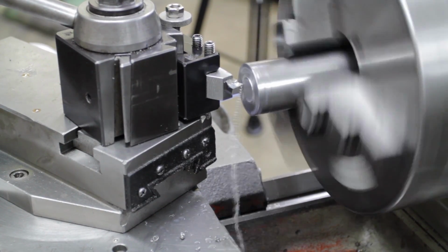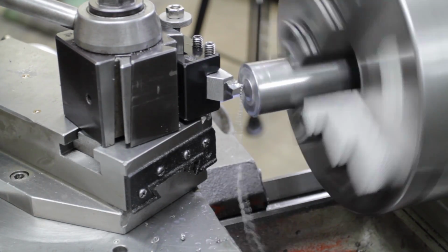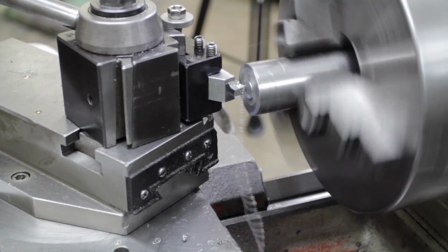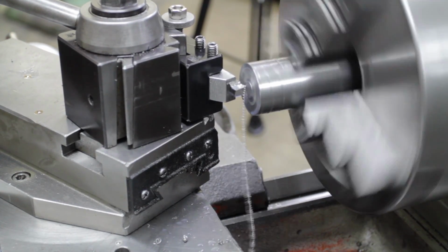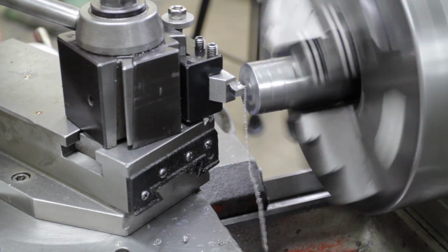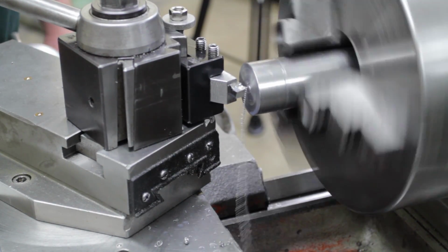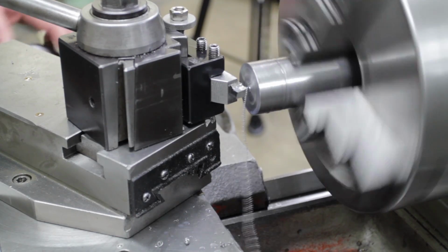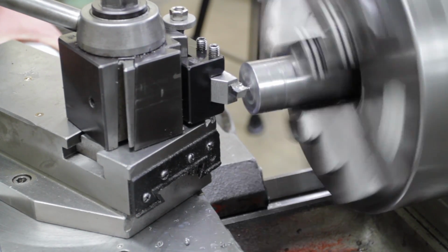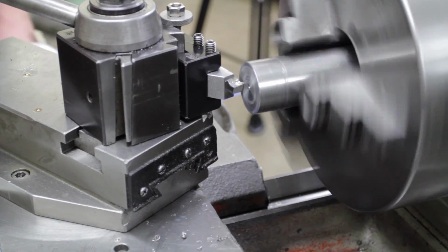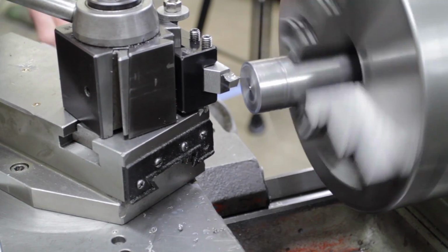So 20 thousandths is a pretty good depth of cut. It's not a big depth of cut, but it's not a finished cut. After this pass, I'm going to bring the tool out and take a 5 thousandths cut. That's 0.005. It's okay if you don't feed to center because we're going to be center drilling it anyway. So I'm going to leave a little bit in the middle. Bring my tool bit back to the outside.